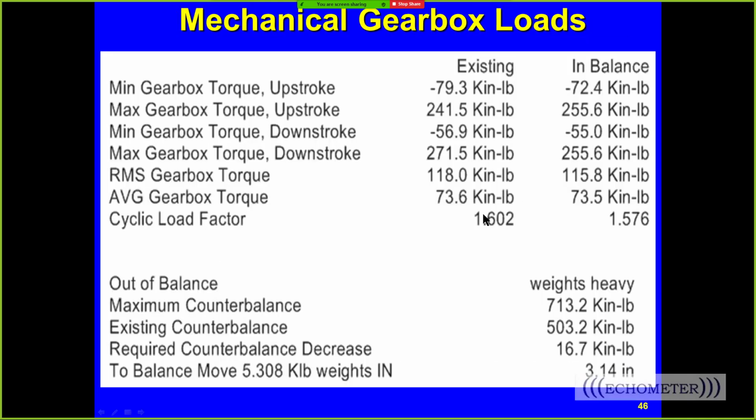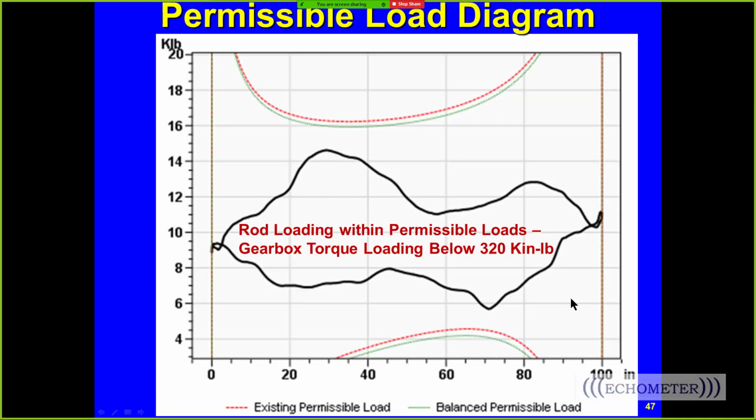Well, this is about a 3% reduction in power, maybe a little bit less than that. But anyway, it would be a small amount. Would 3% power savings justify moving the weights? Well, maybe you wait until you service a pump unit and have them move the weights. So the 3% power savings may not be enough to pay for the cost to move the weights.